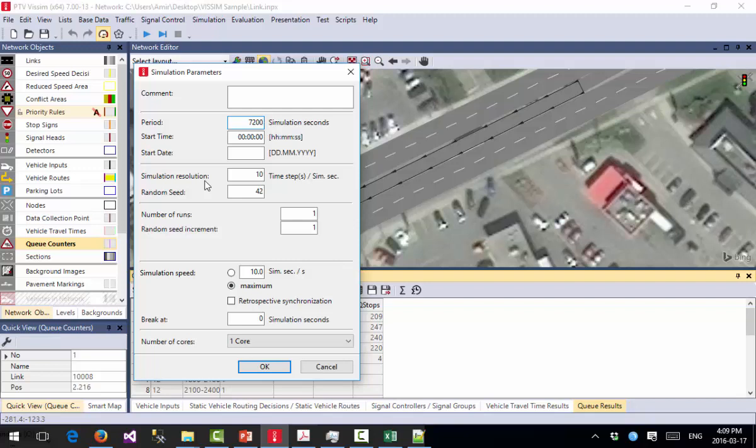if we want to do multiple simulations, we normally do multiple random states and then average and get the results. As you can see, Vissim can do that for you. You can say, okay, for my simulation, I want Vissim to do 5 simulations for me. It will run your simulation 5 times, and each time it will increment the random seed. Then it can do the averaging for you and some other calculations. So that's these two values here.